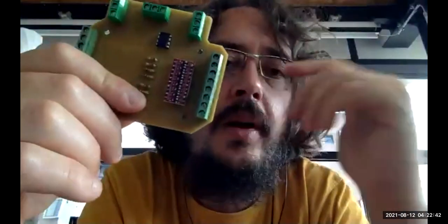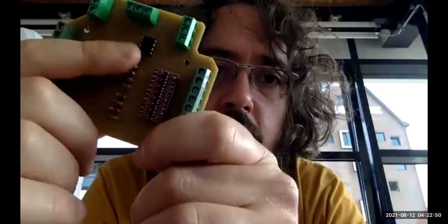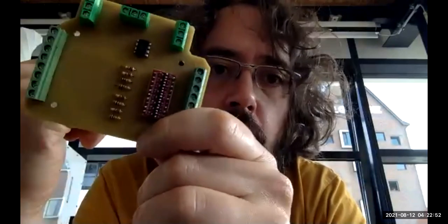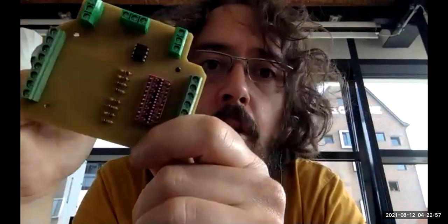So the discussion is a little bit complex. Basically, when there is no signal, this outputs logic level high. It's always pulled high. If the microcontroller sends a low signal, then it goes low, but then how fast it can rise up again is given by the pull-up resistors in the output of the logic converter.